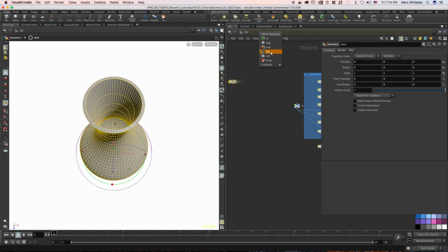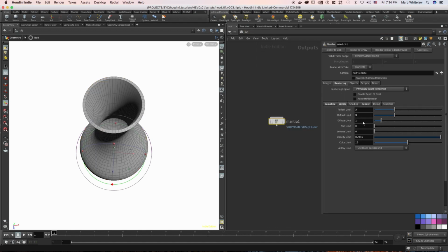So right now, if we have a refraction limit of 3, it means it's going to enter the surface, bounce through the object and to the inside, and then once it hits this edge over here, it's going to stop. We would need to change this to 4 so that it will be able to successfully bounce out of our object and escape again.